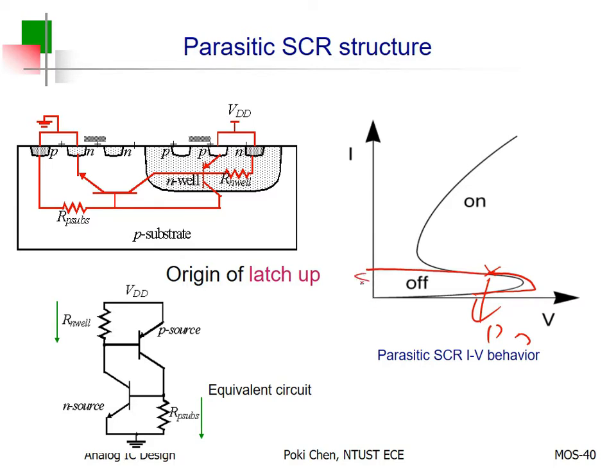And I would like to turn it off. Oh, sorry for that. Here, if we would like to turn it off, it will be shifted to there. It doesn't have any chance to go back, right? So even if you would like to turn it off, you can see a lot of leakage current here. And the chip is more likely to be burned.